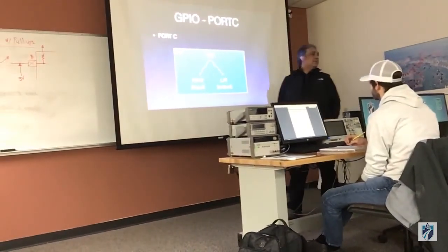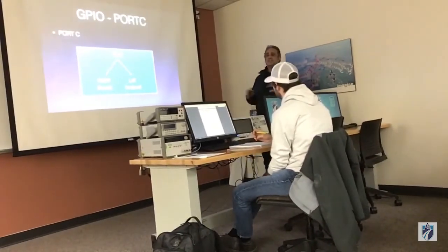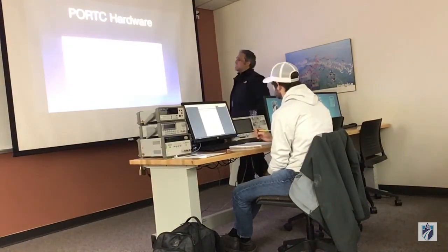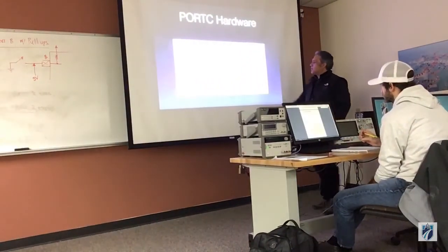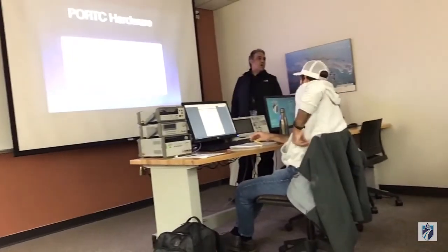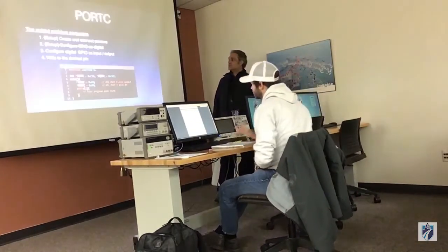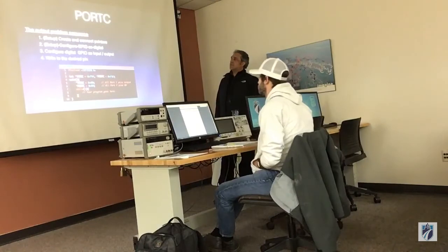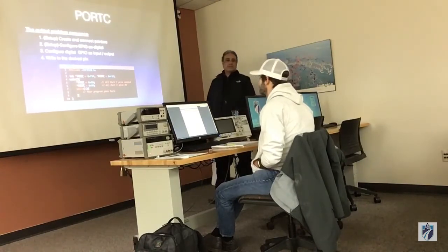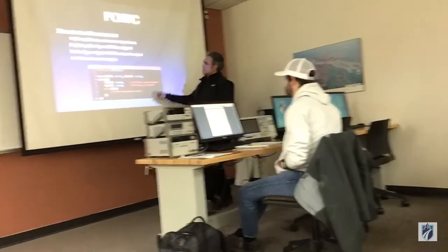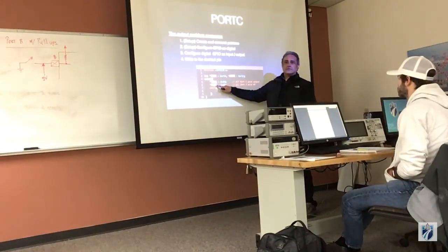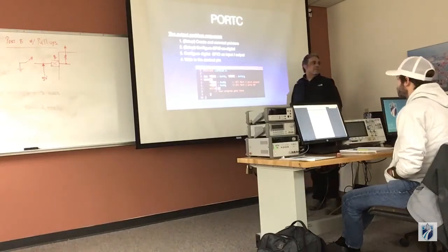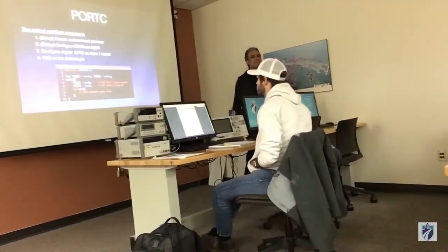Port C. Port C does not contain any analog pin, so it's a piece of cake. Here's port C. It's split between the left and the right side of the micro. There is absolutely no analog ports in it. So, the configuration as digital is not needed. So notice that the circuit is exactly the same, but the AD con disappeared. See that? The AD con is not necessary for port C. See that?